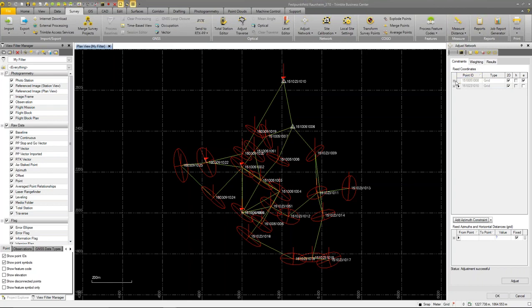Additionally, there's one last thing on these coordinates. I'm fixing those coordinates, so I'm basically saying that I have 0 values for how much I'm letting those coordinates float around. You do have the ability to apply constraints that are non-zero on your coordinates. Let them float around a little bit when you're mixing and matching control from different agencies.